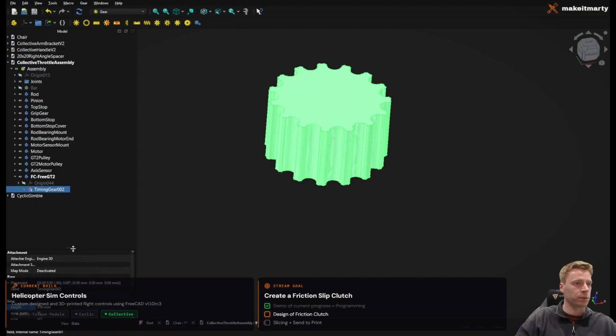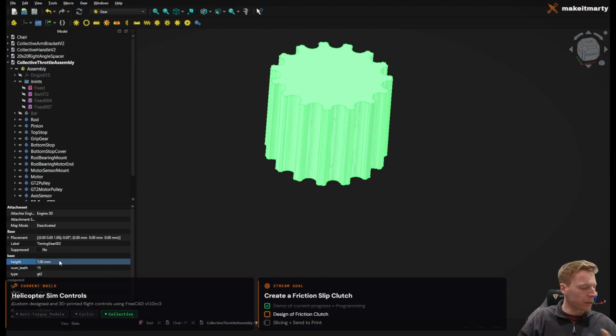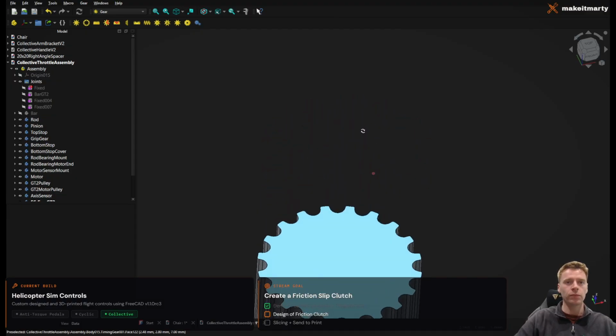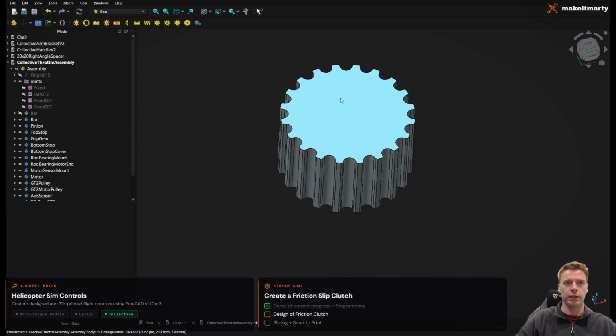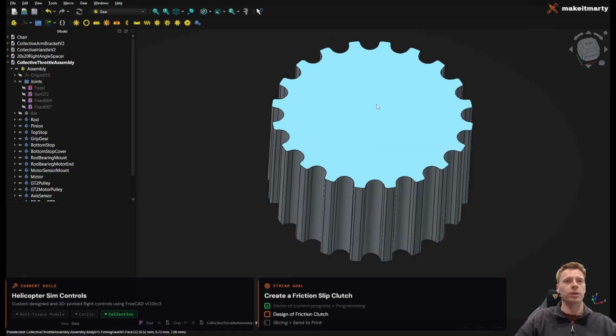I'm going to have a look at the properties here. So let's give it 7mm. I think the belt is 6mm. This is the slightly shorter one, but I'm pretty sure that's 6mm. So let's do 7mm. And then we said 20 teeth. And it's a GT2 type, which is the profile of each tooth. Cool. So this is our gear that we're going to start with, and then we want a bearing inside here.